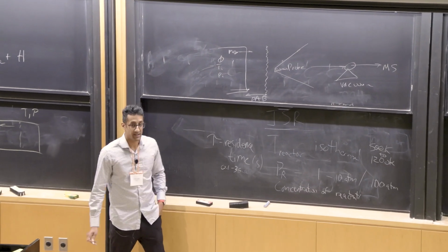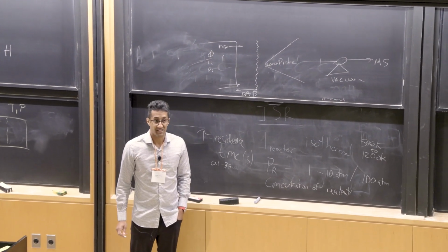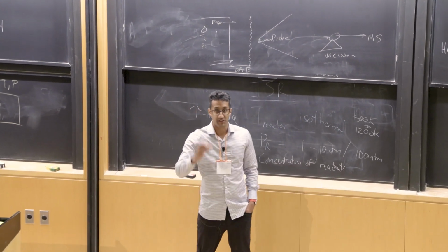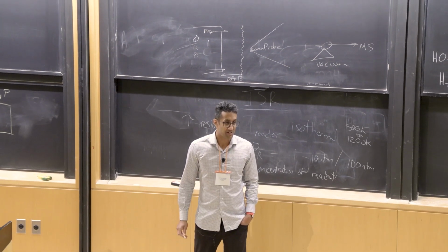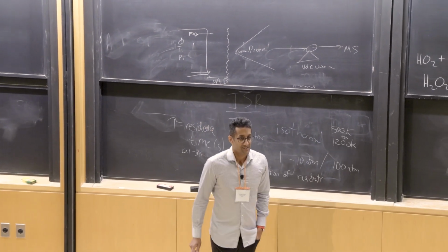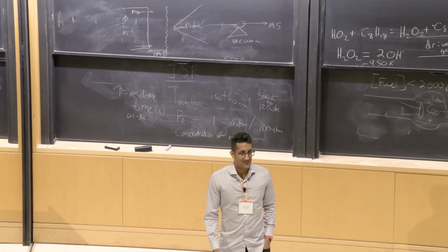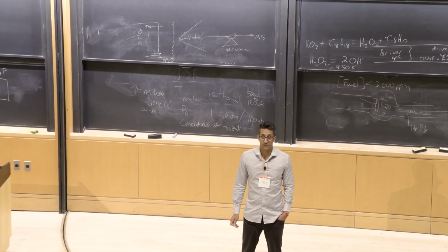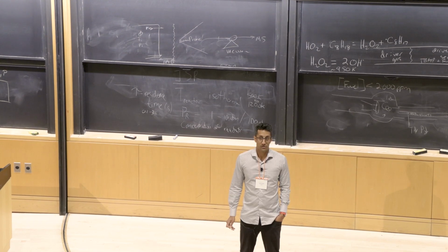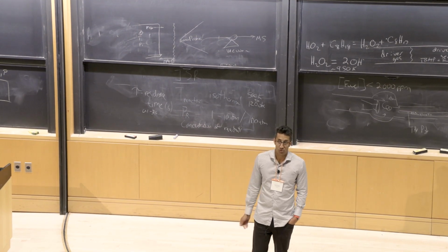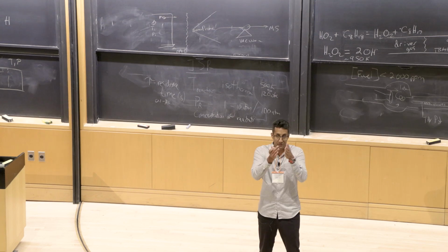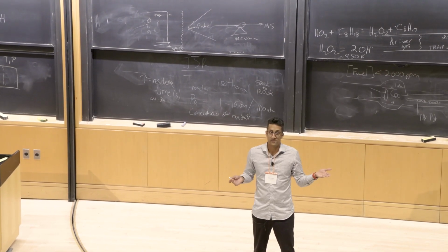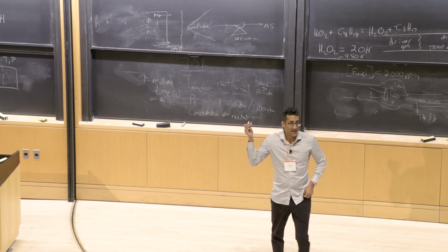Now, he wants to do it at atmospheric pressure because he has a laser. And a laser has a very good resolution. I don't know, what's the resolution on a laser? Let's see, measurements every eighth of a millimeter. Eighth of a millimeter, okay. So that's pretty good, a few hundred micron, right? So it's much better resolved than a cone. So even if the flame sits nearer to the burner, you can do it at atmospheric pressure. Much easier to do an experiment at atmospheric pressure than at low pressure.